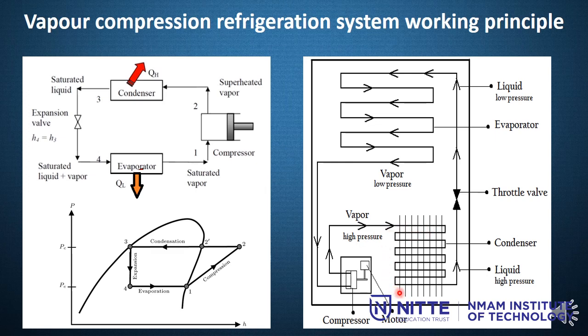The condenser is a heat exchanger and exchanges heat to the surroundings, and now the pressure remains the same. However, the temperature drops down and the refrigerant becomes a liquid. Now the compromise of the pressure remaining the same and not the temperature is done by another compromise, such as that of the state change from vapor to liquid.